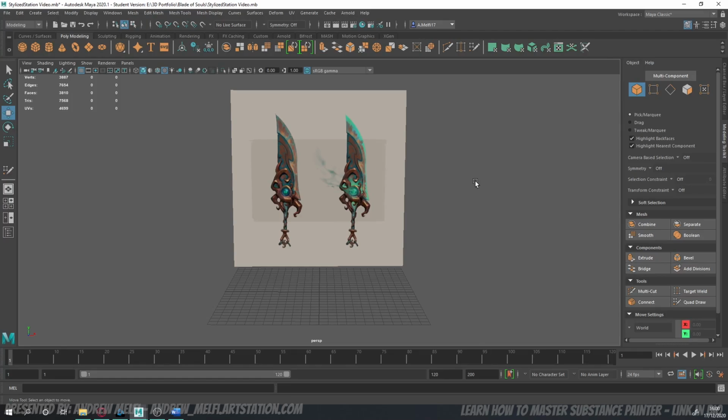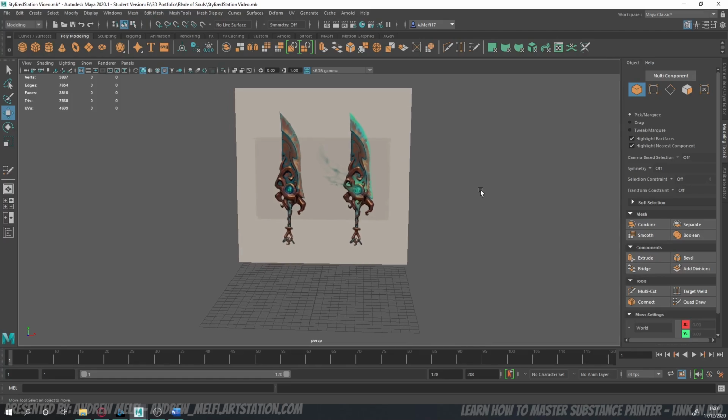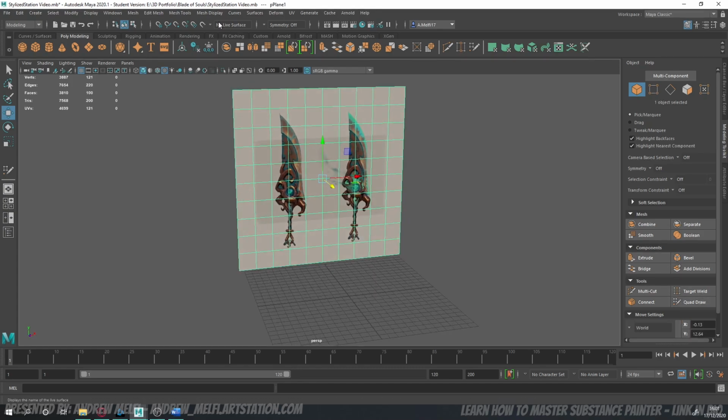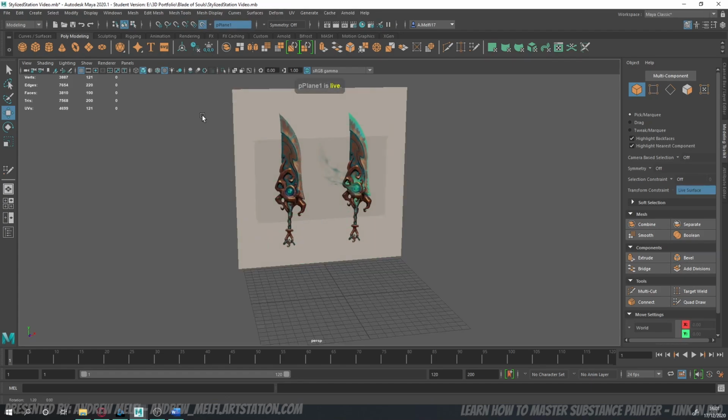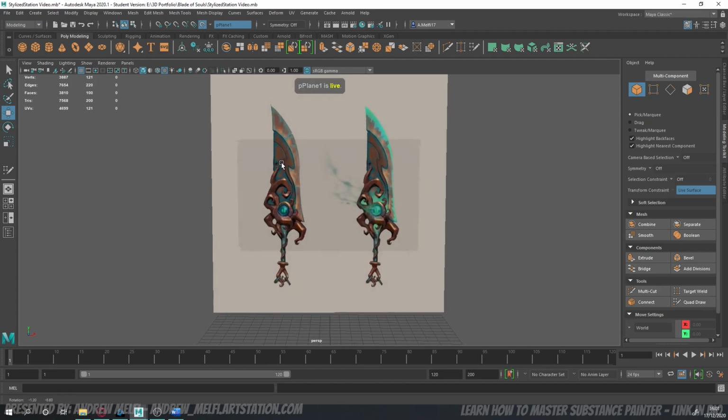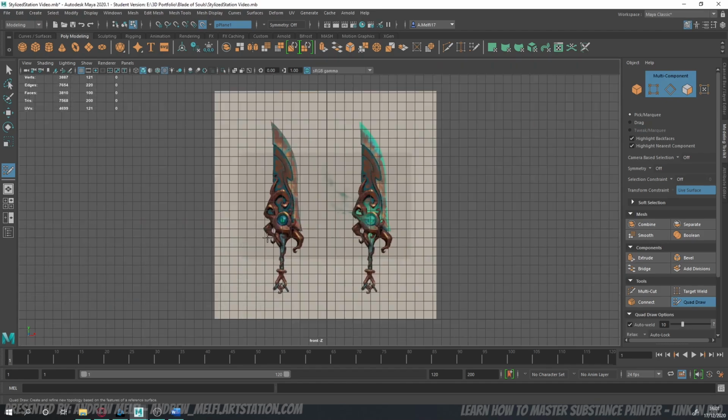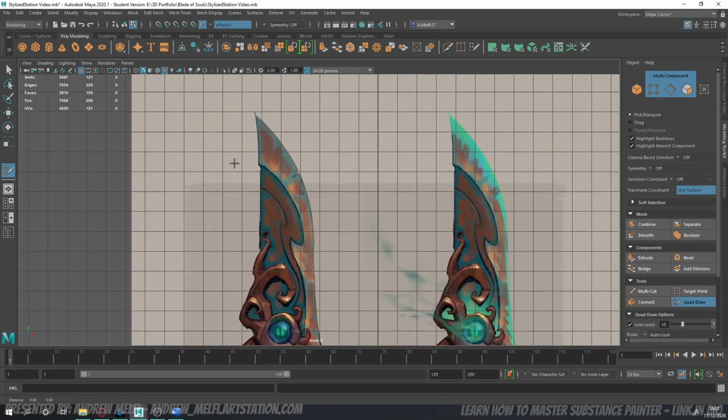Once I had my reference image in Maya, there were multiple ways I could go about modelling the weapon. One being a really cool tool that Maya has called Quad Draw. It's just down here, and first you have to make the object live. So if you just click on this magnet up here, that makes this plane live, so I can't click on it now. Go on Quad Draw. If I look to the front view, it will make it easier.